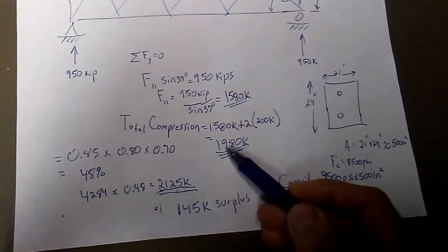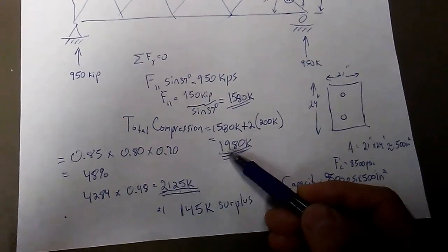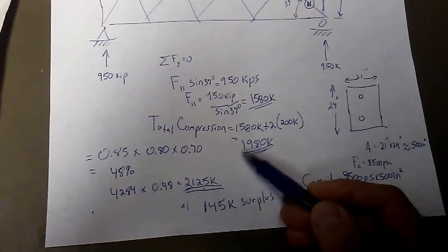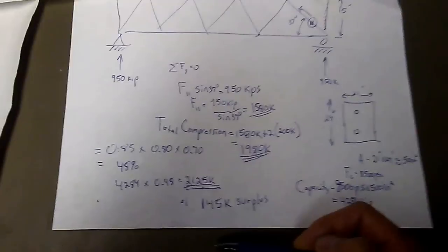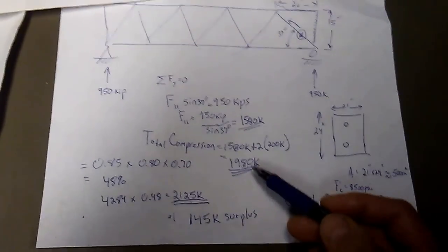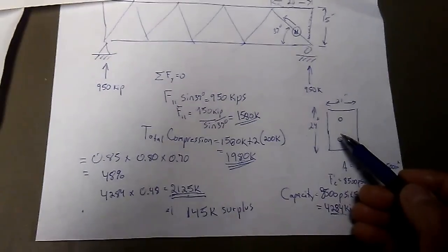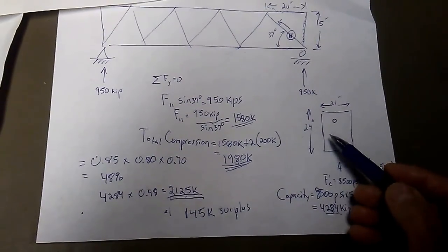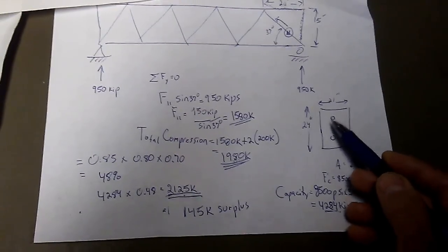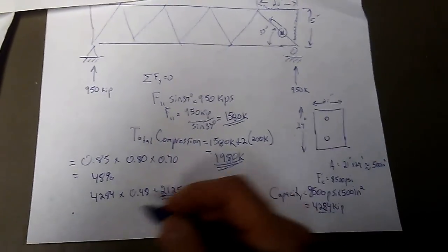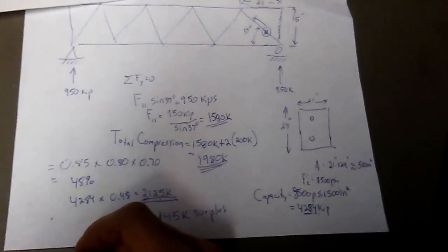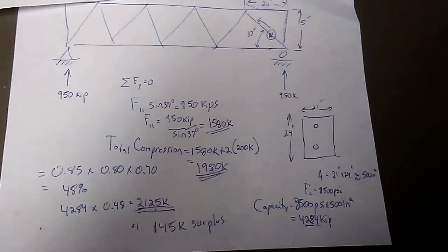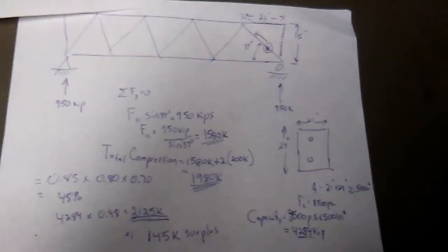So what I think could have happened, that's not a lot of margin for error here, right? We're looking at about a 5% margin, between 5 and 7 or 8%. So what could have happened is if the contractor had not been properly post-tensioning these bars. We know based on the drawings that he was supposed to go to about 200 kips. Now these bars are 1 3/4 inch diameter, and a 1 3/4 inch diameter bar can actually be stressed up to a tension of 400 kips approximately.